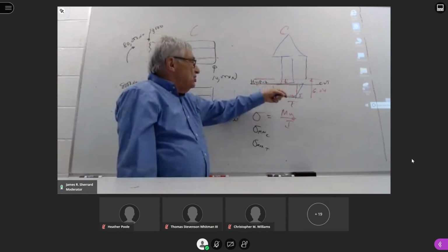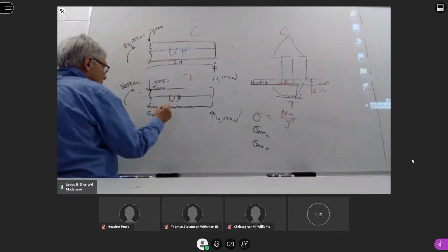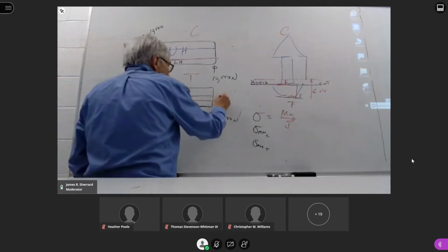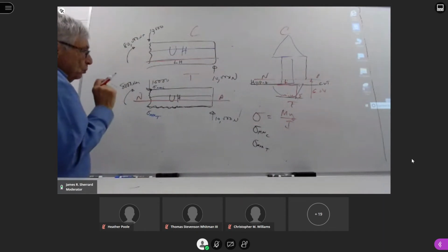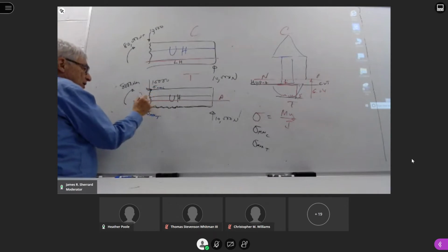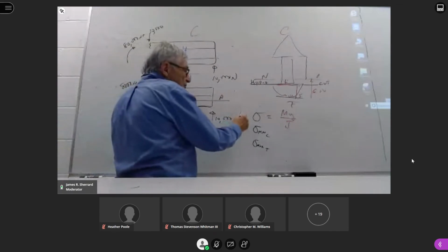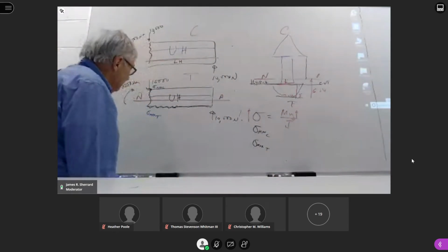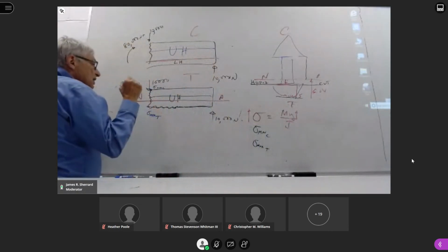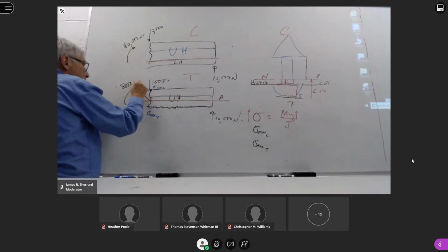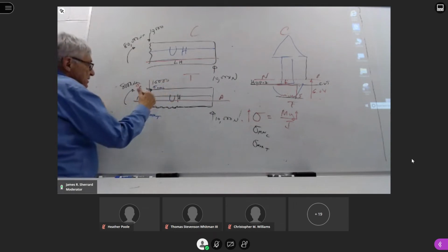We know that the plane stress is exactly 0 on the neutral axis. So if I sketch the neutral axis in here, and again, it's this same neutral axis here. Because remember, the neutral axis is really a neutral plane. Okay? We know that on the neutral axis, the stress is exactly 0. As we leave the neutral axis and go to the upper member, this value increases because y is increasing. So at exactly where y is equal to 0, there is no stress. As we go up, this varies linearly. So this is a plot of sigma, and in particular, this is compressive. Okay? So we know compressive tends to go back like this.